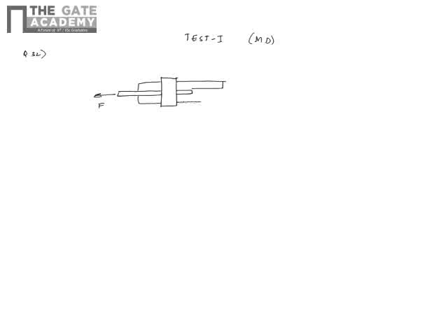So it's kind of a double shear joint. Okay, and you are applying F by 2, and this is how your rivets are formed. Now what is asked is the ratio of crushing stress to the shearing stress for this rivet, and this entire thickness is L. This thickness is L, and this is also L.